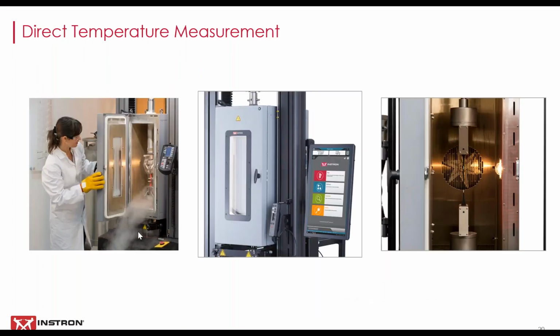Many products have requirements to be tested at non-ambient temperatures to simulate environmental changes that might occur during use or transportation or storage. A typical configuration for testing at non-ambient temperatures is to put the specimen and fixtures into an environmental chamber, such as the ones shown here. The temperature can be set using the built-in controller or through the software. Using the software is nice because it allows the temperature to be changed during the test if necessary.